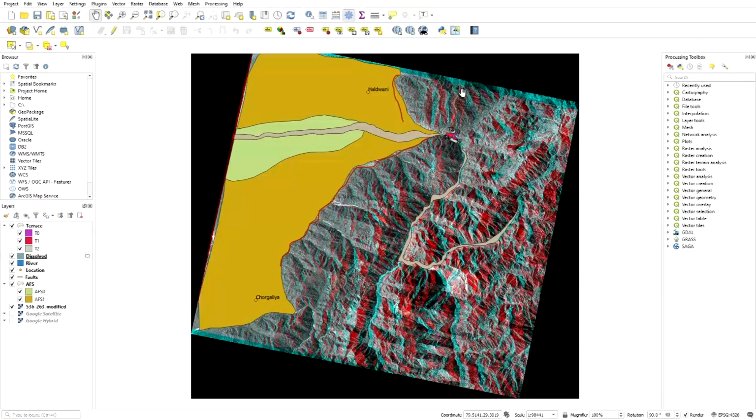or the rivers, the river terraces, alluvial fan surfaces, and we have also marked the lithology for the area. For the lithology part you can simply use the GSI map, where they have mapped all the lithology for the Himalaya. So, you can simply use their map. First you have to georeference their map, and when you georeference the GSI map, you then simply extract information by the digitization process. So, you can mark all the lithology on your respective area.